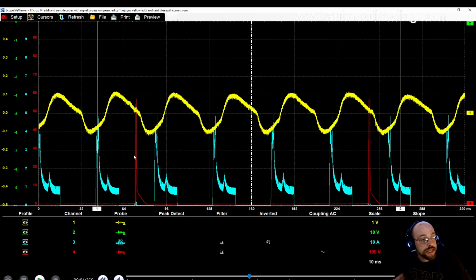You can actually see, here's our injector 1's control hit that's on the red, as I mentioned in the connections. Here's our flow curve for injector 1. There's where the injector opens. Here's where the injector snaps shut and the pressure rebounds. Not only does the pressure rebound, you can actually see the spill solenoid current is coming in here.